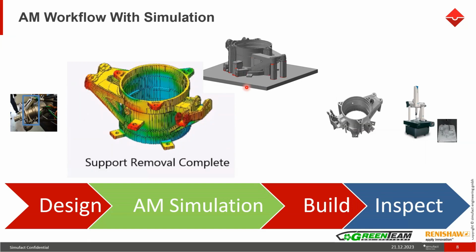So here you're doing this build. Is there any kind of flaw or possibility of defects? Yeah, there can be possibilities. If the laser is not melting at a particular region, there can be lack of fusion at that region, so that may cause some defects. There are some machines which can detect those defects actually. That is manufacturing defects.